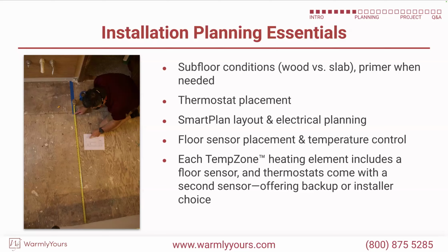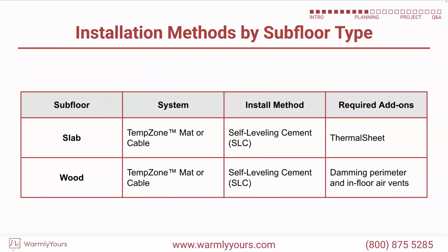We're not going to heat under beds a lot of times, or under a solid bottom box. You can heat under a bed. In fact, in this example, we do, but we had to know that in advance and how we're going to attack that. Also, you never want to put it under anything that's permanently attached, like a wardrobe. If a wardrobe is going to be sitting on the floor for the whole length of the room, you don't want to heat under that. So you stay away from stuff like that. And in bathrooms, you stay out from under vanities, you stay out from under those types of areas. So get us the drawing, and then we can run with that.